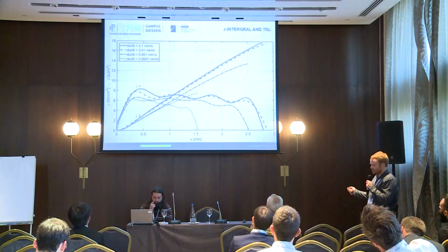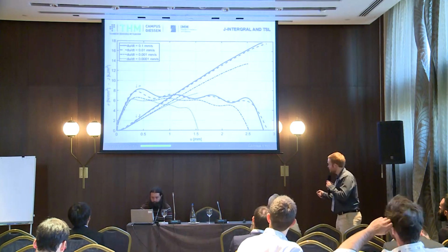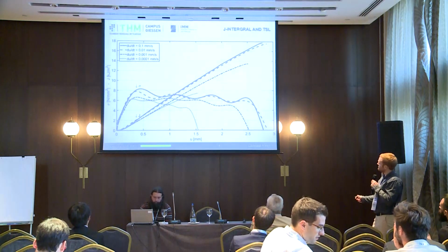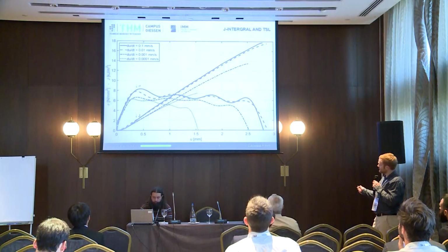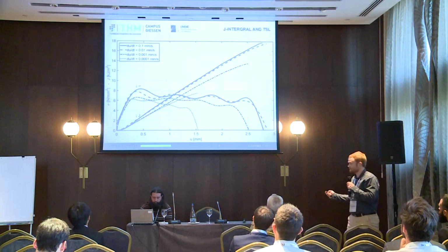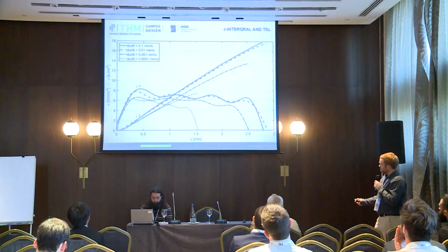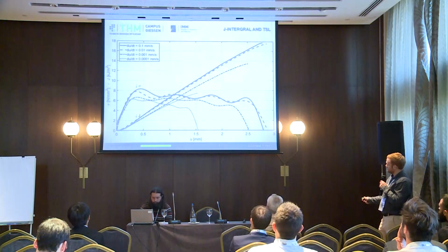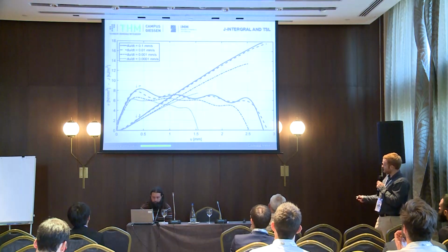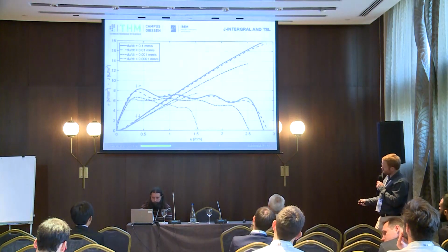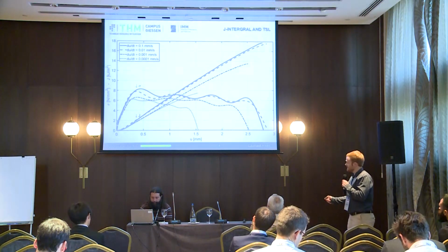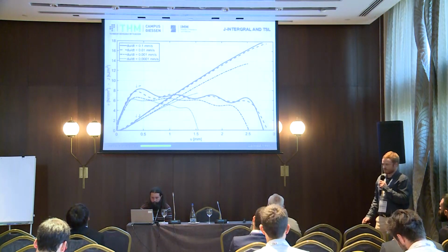If the crack opening velocity is increased now, you see that the maximum value of J is rising. So fracture energy is rising with rate. This is an expected result. If you look now at the traction separation laws, they look trilinear, trapezoidal, but the initial portion which we used to calculate the stiffness seems to be nearly unaffected by rate.